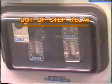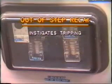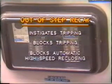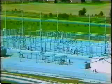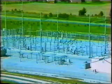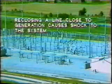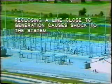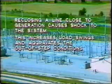As we have already seen, the out-of-step relay may be used in several ways. That is, one, to instigate tripping, two, to block tripping, three, to block automatic high-speed reclosing. Now, why would we want to block the reclosing action when we have earlier pointed out that fast reclosure actually assists stability? Well, this is true, but once the system has become unstable and the out-of-step conditions exist, then reclosing a line close to a source of generation may well cause a shock to the system that increases the load swings and aggravates the out-of-step conditions.